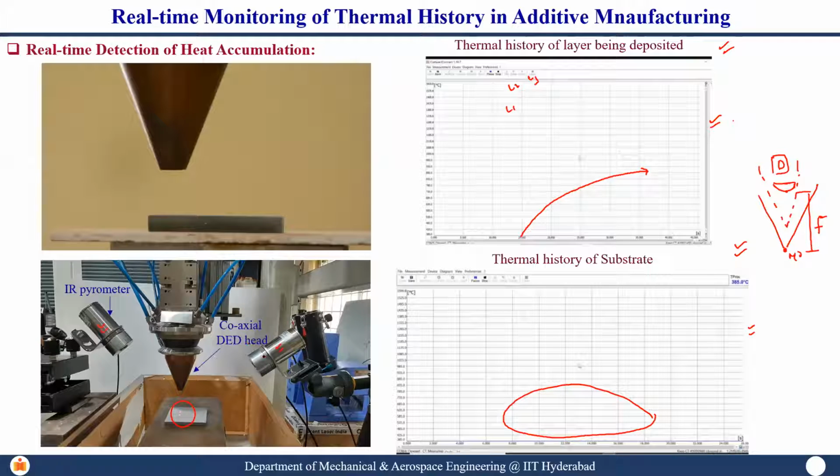Each pyrometer has two diodes along the diameter, and whenever both of them are focused at one particular point, it signifies that you are exactly at the focal length of that lens. If you are not at that point, it will not give you any reading, even if it varies by 5 mm. So this is done by using the guide lasers provided on these pyrometers.